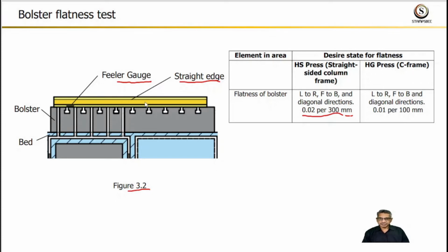Place the straight edge on the surface. Ensure the butting of the surface. Identify the lowest point and measure the gap with the help of the feeler gauge. If the gap is more than the allowable range, corrective action is required. The general corrective action is manual leveling of the surface or machining of the surface.